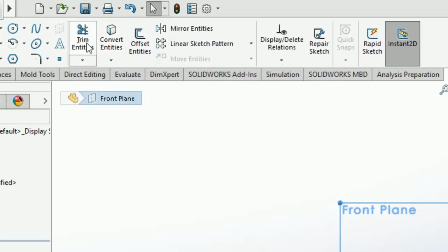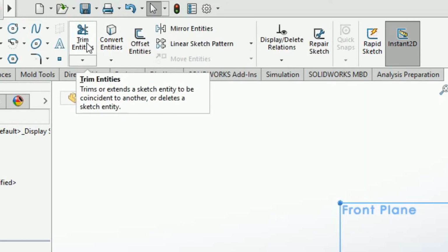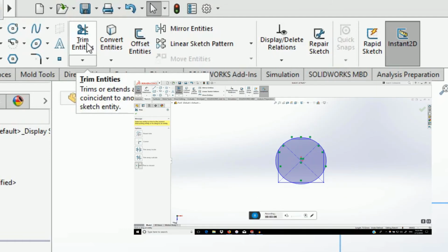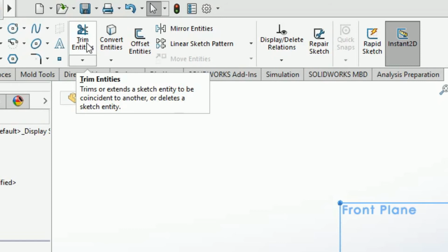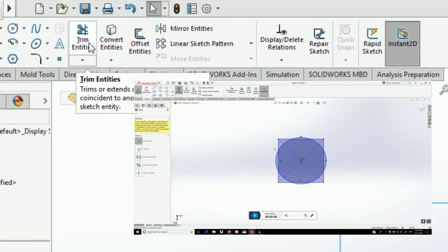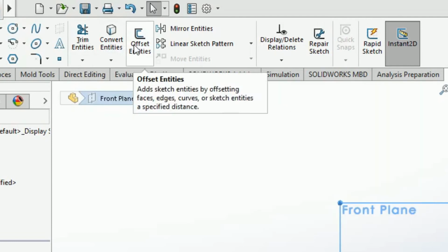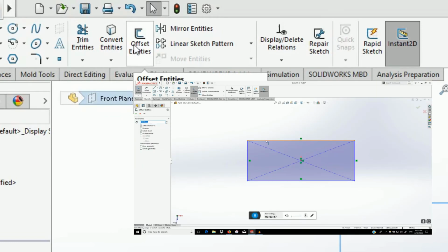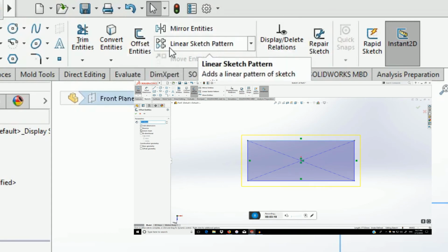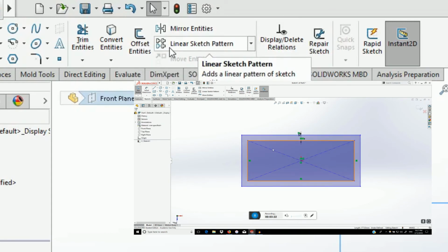If you want to cut a plane or feature that sticks out, you can do that with the Trim Entities command. It can work in many ways, so choose your preferred one by trial and error. We personally prefer the Power Trim option that cuts all the features the cursor meets while pressed down to the closest meeting point. You can offset some sketch features by a set distance with the Offset Entities command. You can choose whether to keep or discard the initial sketches.